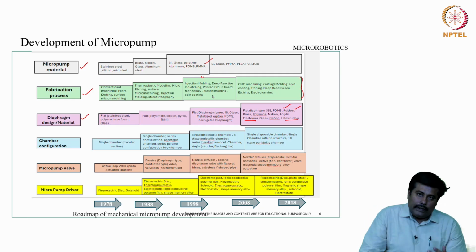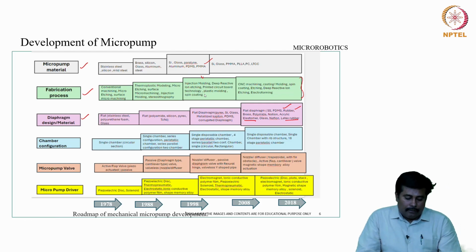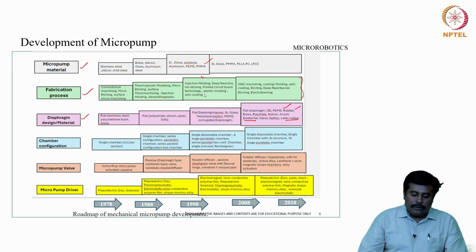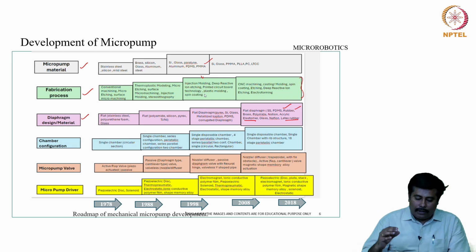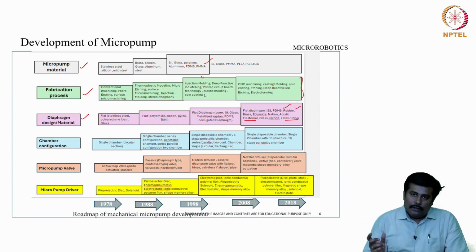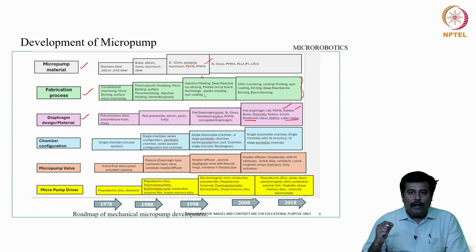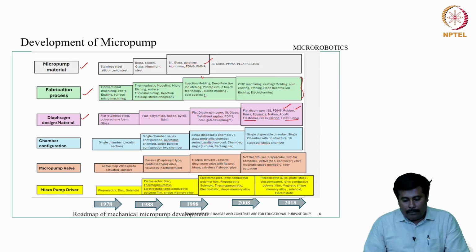So, when I try to classify this micropump from the valve perspective, we have an active flap valve, that is a piezo-actuated passive structure which is deployed. There is also a kind of passive diaphragm-type cantilever valve, and valveless systems are deployed. In certain cases, there is a nozzle or a diffuser, or a passive diaphragm valve with flexural hinge, and valveless Y-shaped pipes are deployed.